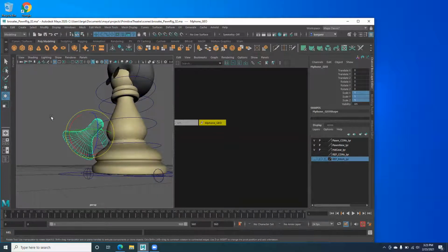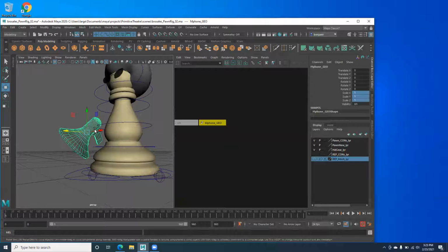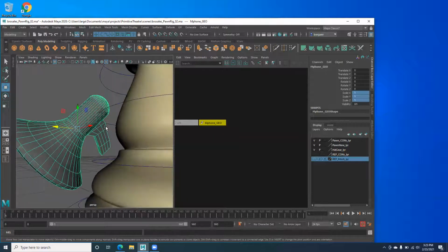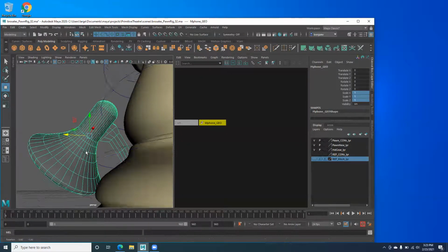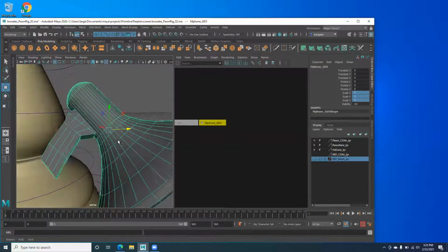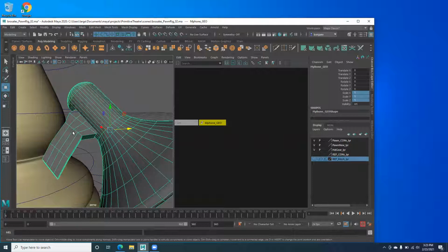The other thing I need to do is, in fact, I should have done this before I moved it, but I can just kind of eyeball it. I need to have the center pivot not right in the middle of the object, but where it's actually going to pivot. So if I have a megaphone in my hand, like if this phone is my megaphone handle, I'm going to grab it here and the megaphone's out here. I'm not going to rotate it from right here. I'm going to rotate it from where my hand is going to move it.